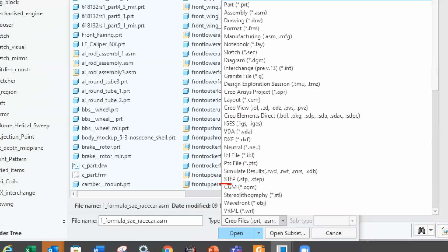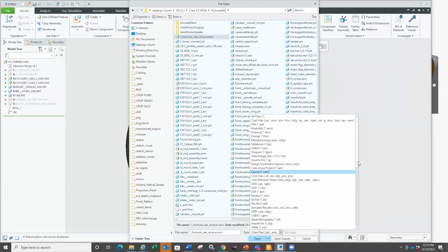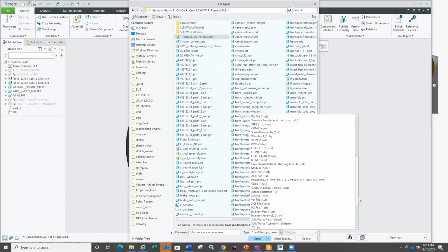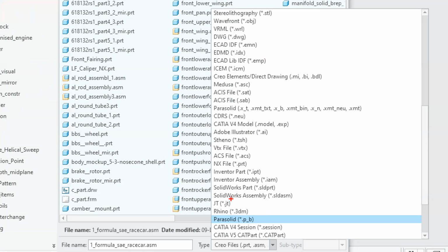Many of us are used to STEP files and IGES files. That still works. During my industry days, I used to sometimes get better luck with STEP compared to IGES. It used to vary depending on how complex the geometry was. But instead of using neutral files, if whoever's sending you the file is okay to send the native file, I would rather just try opening